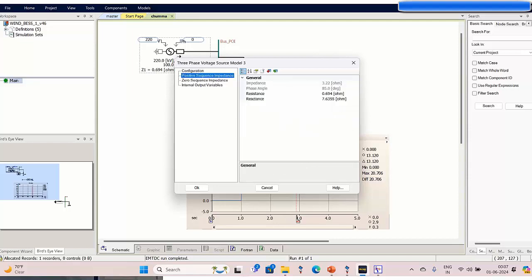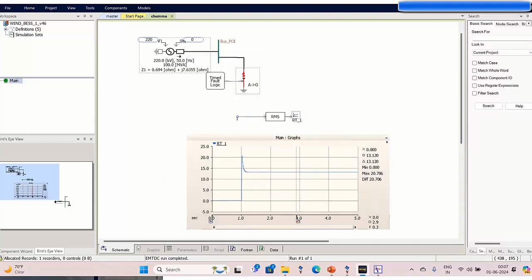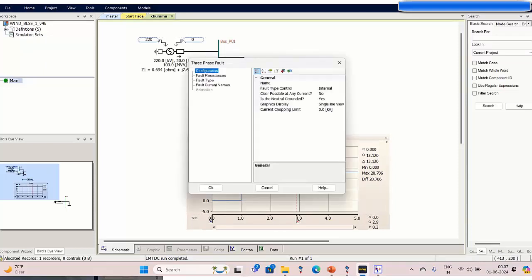Then coming to positive sequence impedance, whatever value we have calculated in terms of ohms, I have substituted here. Zero sequence impedance, the same calculation, the results we found here are available, and I already ran this model and found a single line to ground fault here, 13.122. Have a look at this. A to G line to ground fault is applied here. I'm getting this 13.122.